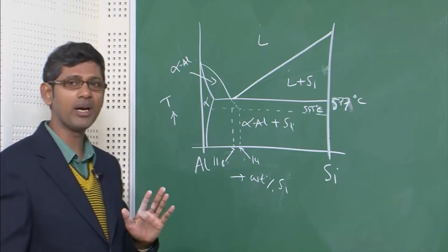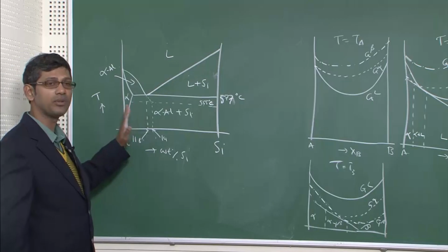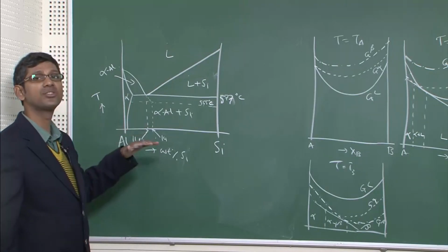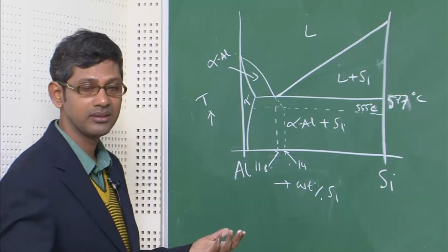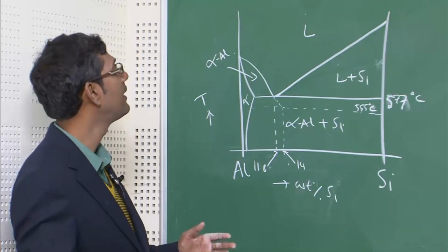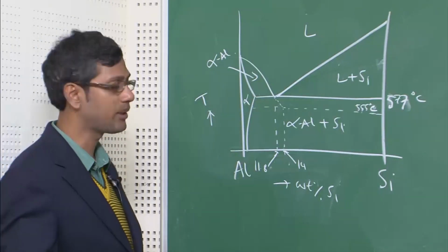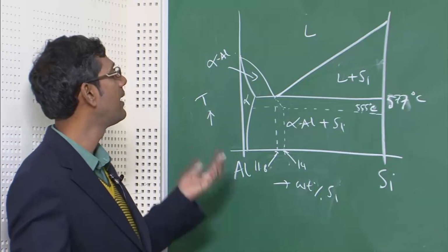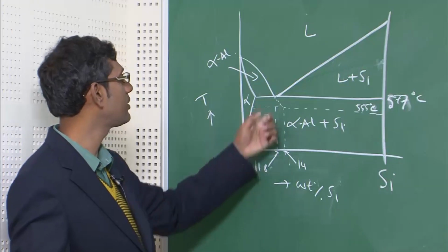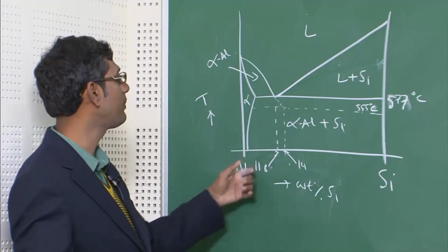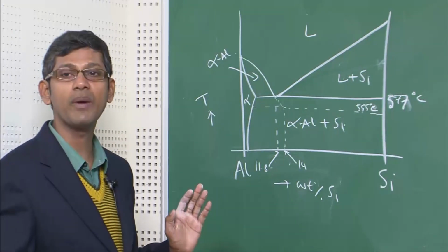So basically what it boils down to, in a short way, is that if you add sodium, strontium or something, it basically makes the nucleation and growth of silicon difficult. Growth of silicon becomes difficult, and that is why you need more undercooling, because you need to provide more energy to the system, and then the same alloy which was a eutectic alloy for aluminum silicon, when you add sodium becomes a hypo-eutectic alloy, and you get to see a lot of aluminum dendrites.